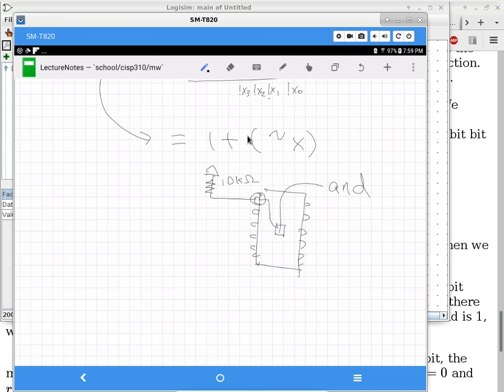Yep. So when you said don't leave any inputs unconnected, is the general rule of thumb to connect a 0 or a 1? It depends on whether it's an AND gate or OR gate. If you're dealing with an AND gate that has way too many input pins and you don't need all of those, then you have to connect a 1, because 1 is the identity of conjunction, so you can hook up the inputs of an AND gate to 1s and not affect the result of the conjunction.